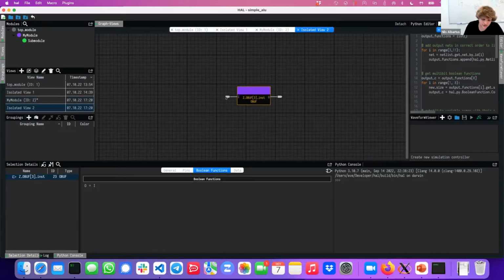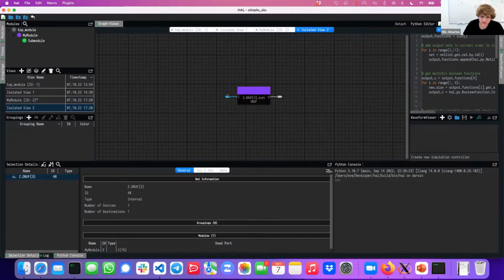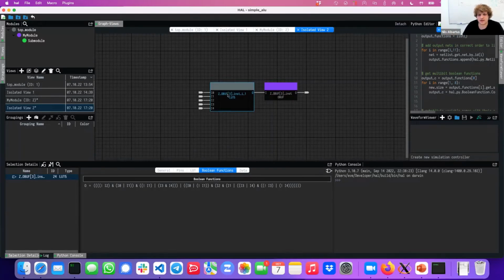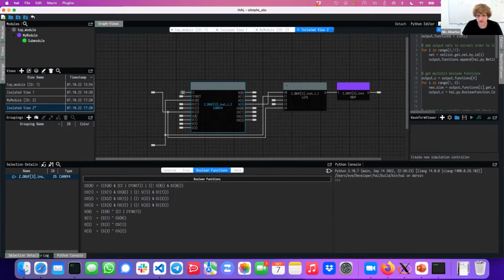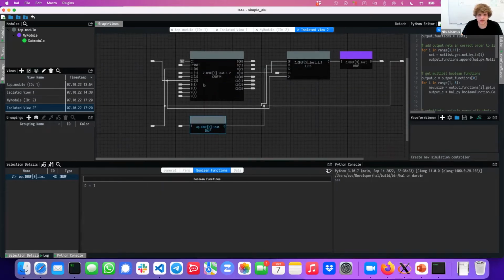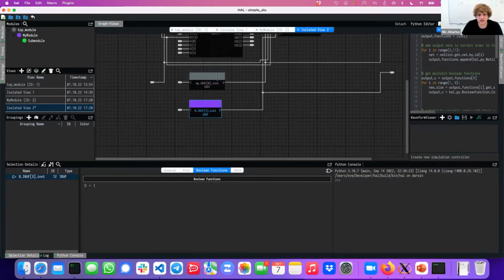And what you can now do is click on these input ports, and with the arrow keys on your keyboard, you can add the gates that are in front of or after the gate. So basically you can traverse the graph in a limited view where you can click all the gates that are relevant for your analysis right now, so that you're not overwhelmed by the entirety of gates and can analyze single parts of the netlist. So you can go farther, on till the very end, till you reach the inputs.